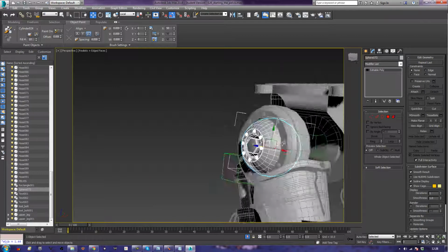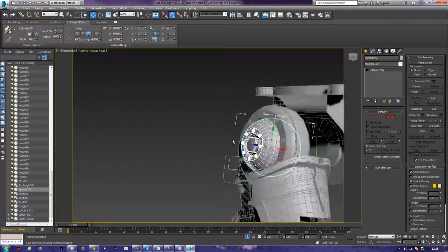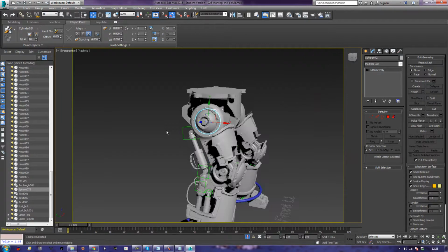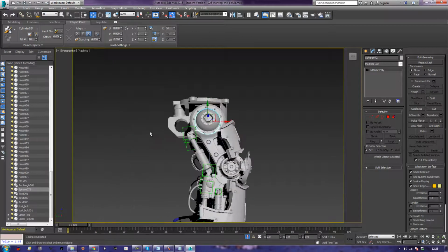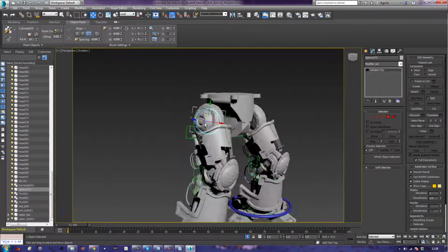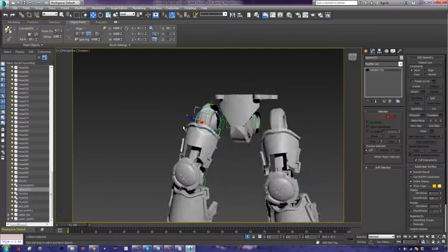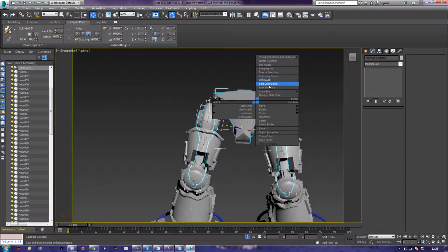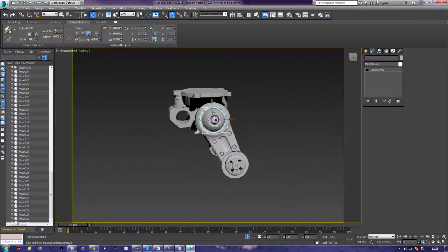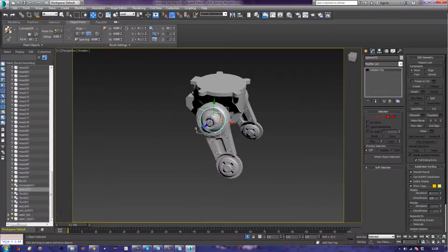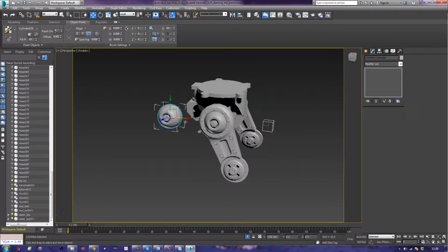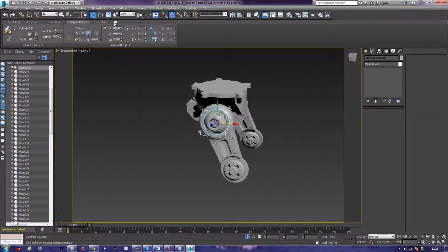Alright, so we have this end detail piece here, which is exactly what I was heading towards, and it does give it a nice degree of solidity. What I'm going to do next is basically isolate these parts, so hide unselected, and I want to make a copy of this as well, along with its attached piece. Ah yes, local, forgot about that. It moves them both on their individual local axes, you see.